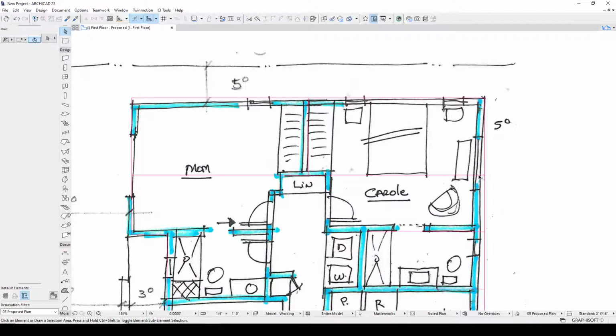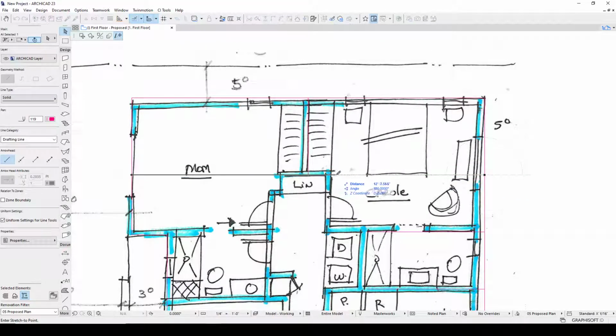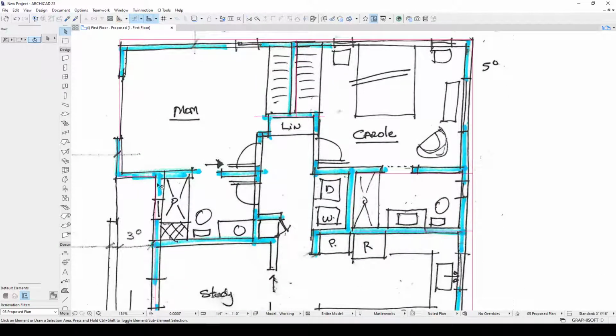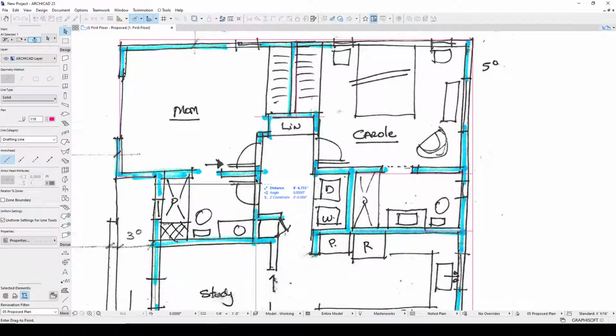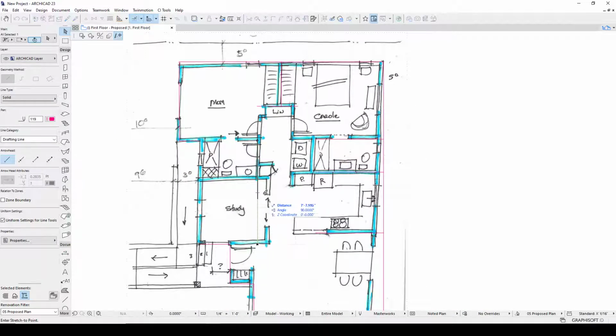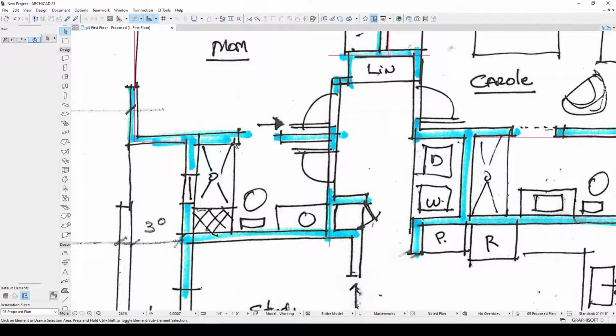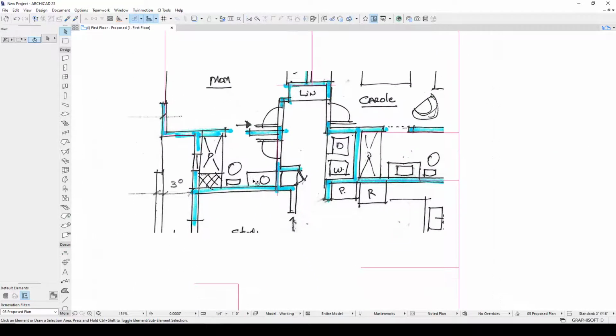And obviously you could do this with walls as well. It's a lot less burden just to run lines, and it's very fast to convert them to walls when we're done. And normalize that to 8.6. F9, copy this up, and looks like a 5.5 foot bathroom there.